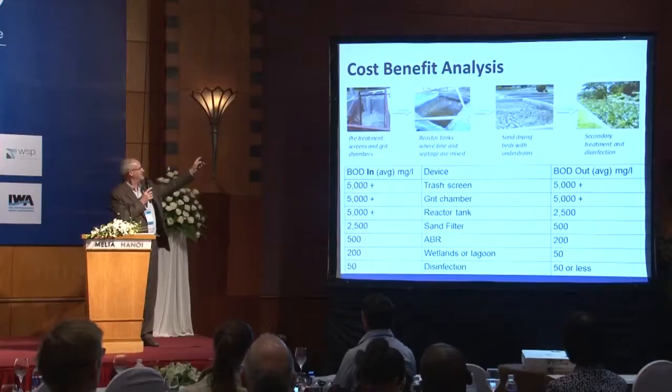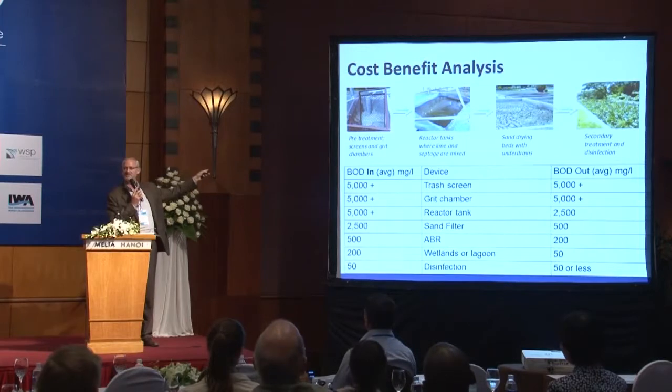So we have pre-treatment screening for the sludge that comes in, reactor tanks, sand drying beds, and then secondary treatment through a constructed wetland cell or even a sewage lagoon. And these will be undertaken in the 14 communities where we're working.